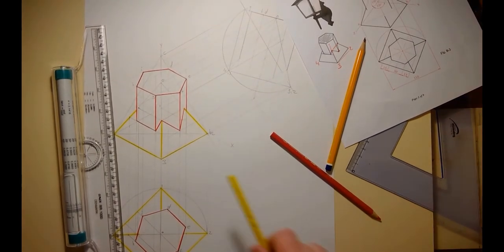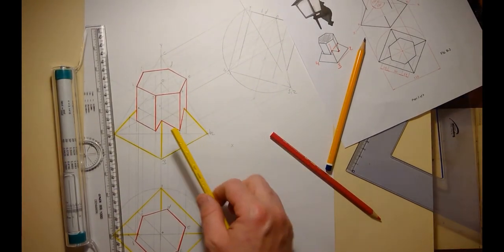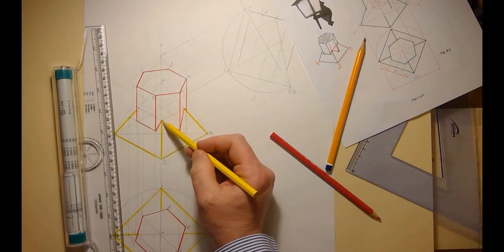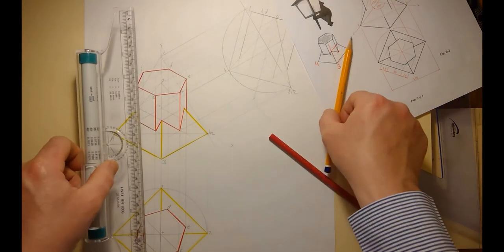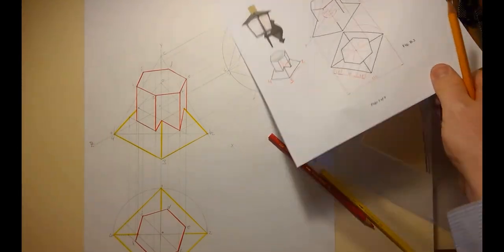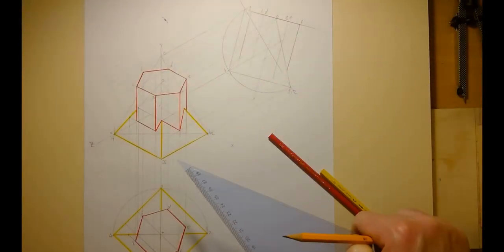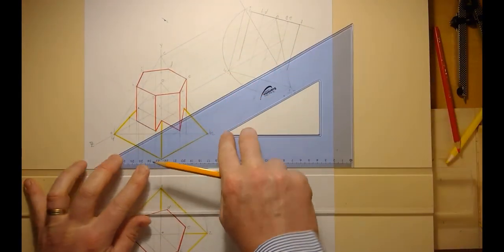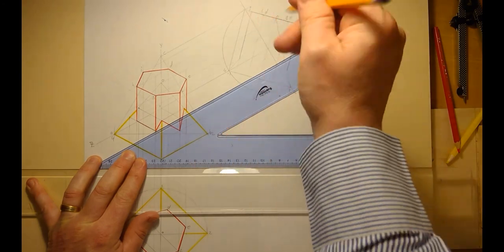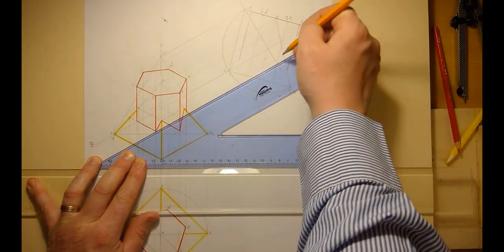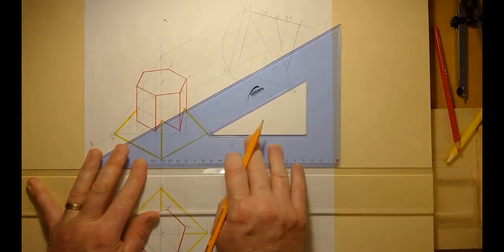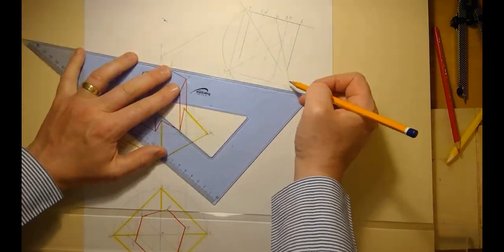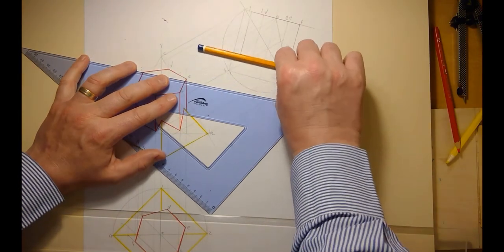Now, after that, just finish off my elevation. All I need to do then is project from my axonometric up to my elevation to basically locate this line here. And then it'll slope up to that guy, and that'll be it for my elevation. So just project back up at my 30 degrees, back up into my elevation. And that's going to give me the location of those points there. One was all I needed because it's basically level with that line going across.